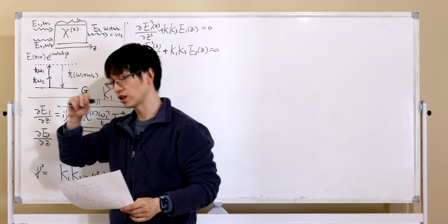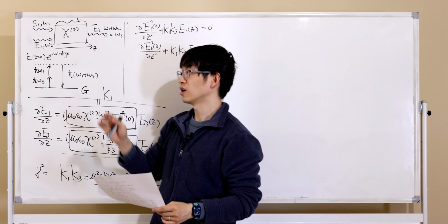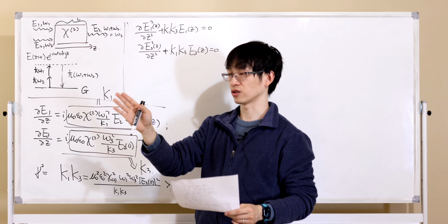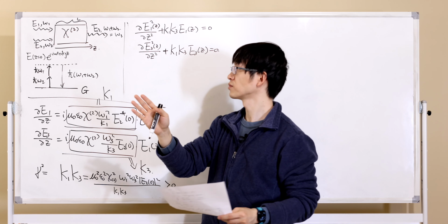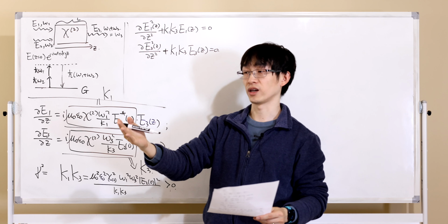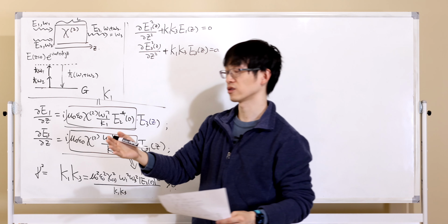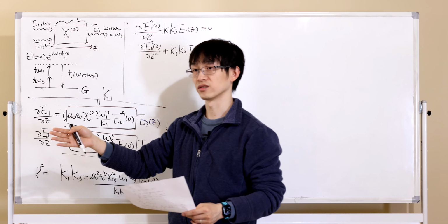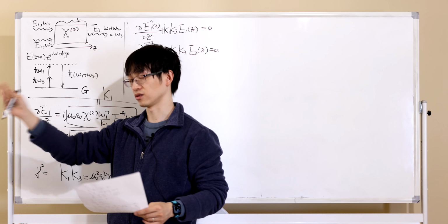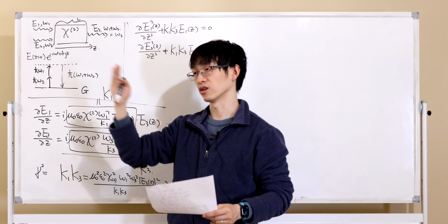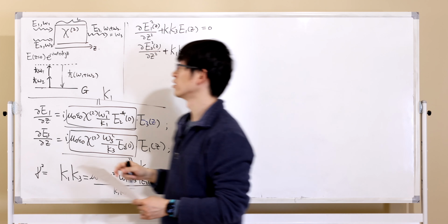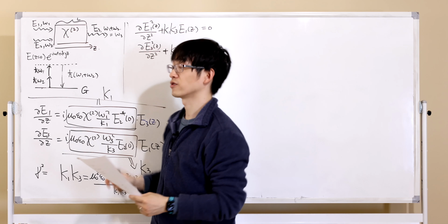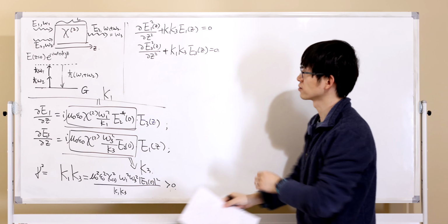Right now everything is digitalized. Still, in electronics, people have signals at, for example, the 1 gigahertz band. The way you can have 5G or in the future 6G is that you upconvert that into, let's say, 50 gigahertz. At 50 gigahertz, there is much larger bandwidth, and you can put a lot of 1 gigahertz channels there. That's a use of sum frequency, not very useful in the optical domain, but very useful in electronics.